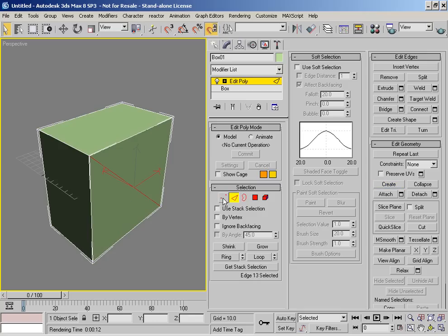So you need to insert a vertex on an edge, create a vertex, create an edge going to that vertex you just created. Now when you refine it, that will create a problem because there'll be a pinch there, because you've got a 1, 2, 3, 4-sided polygon, even though it's a weird 4-sided polygon, and 2 tris. So again, bear that in mind when you're actually modeling.